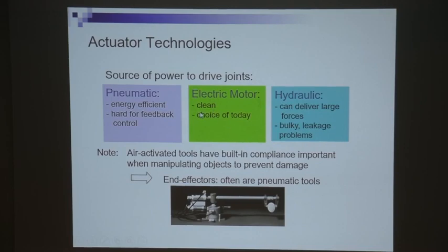The electrical motor is clean, and on the other end you have the pneumatic and hydraulics. The pneumatic one is more energy efficient, but it's harder for feedback control. The hydraulic one can deliver a large force, but it tends to be bulky, and there may be a leakage problem. But all these are general. When people ask you why the electrical motor is used, it's typically because of this general perception of the different motors. Depending on your application, you may choose to use a hydraulic motor.